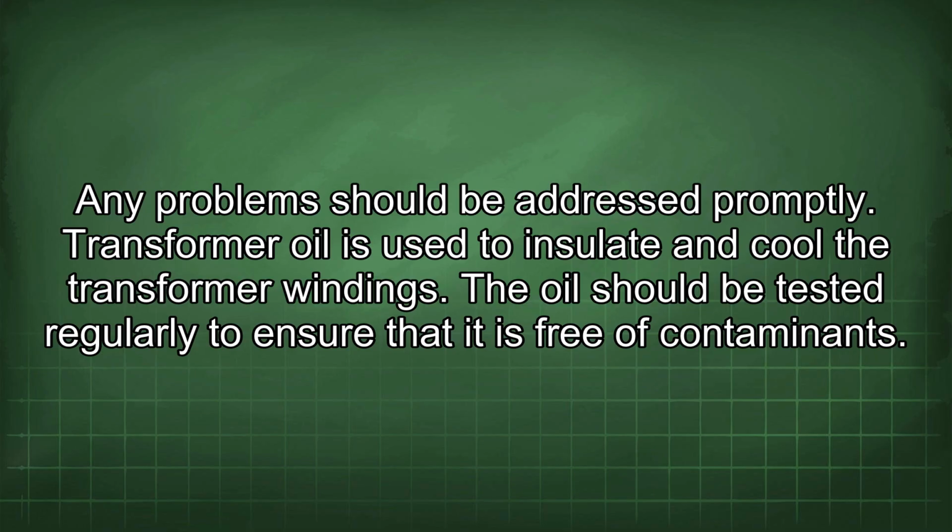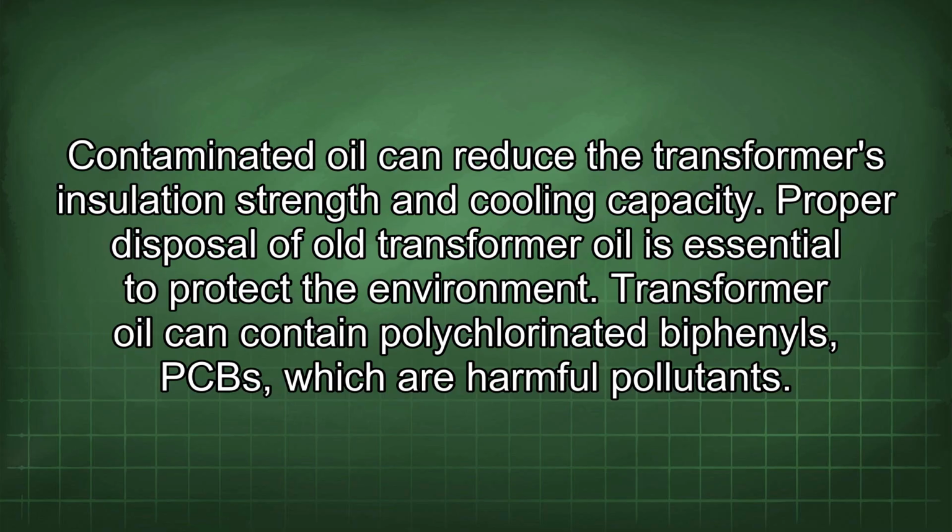Transformer oil is used to insulate and cool the transformer windings. The oil should be tested regularly to ensure that it is free of contaminants. Contaminated oil can reduce the transformer's insulation strength and cooling capacity.